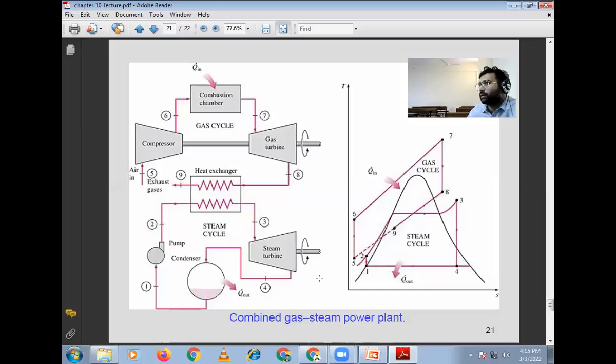Like yesterday, I got an idea about another project that can be done in this case. You can write a program, either in C or Python. In that case, as input you can take the boiler pressure, the condenser pressure, and the condition of steam. Only 3 inputs you will take, and directly your program will give you the efficiency. For that, I don't think much coding is required. Simple, 10 to 12 lines of code will be sufficient. But you have to give the input of the steam table. Okay.